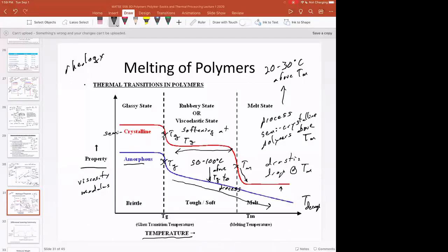And you say, well, do you have the rheology data on this? Or do you have the melt flow data on this? This type of plot from rheology sets you up to understand the modulus or viscosity versus temperature to figure out, A, where the thermal transitions are, but then figure out what is the characteristic viscosity that you need in order to process this polymer.